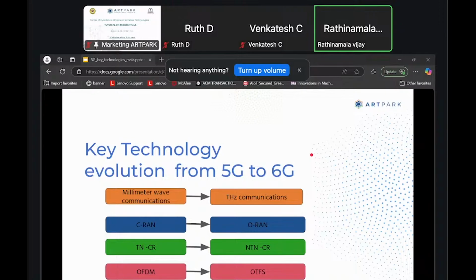That is where the radio access network will evolve with many open standards that define the interfaces between DU and CU, and DU and RU, and so on. In 6G, we will also see that we'll be moving from the orthogonal frequency division multiplexing scheme to orthogonal time frequency space techniques to get good performance under time-varying channels.